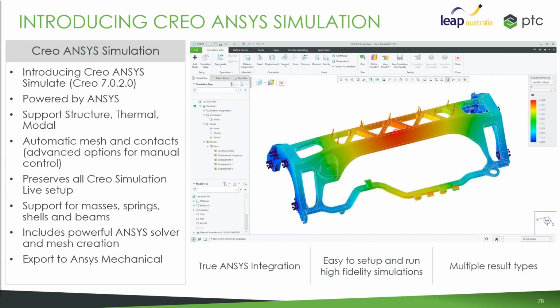On the Creo ANSYS simulation side of things, this is something we talked about last year when we did our Creo 7 launch events. Creo ANSYS simulation was introduced with Creo 7.0.2, late last year, same as the cloud-based generative topology side of things. This is again part of the PTC ANSYS relationship. This is bringing the ANSYS Workbench engine into Creo. At the moment it supports structural, thermal, and modal.